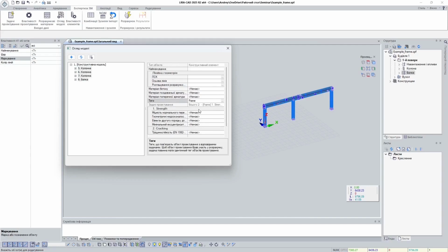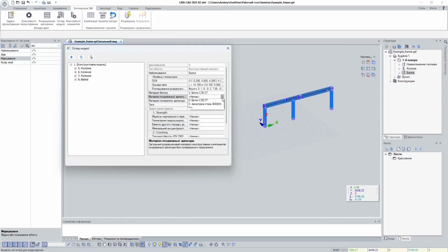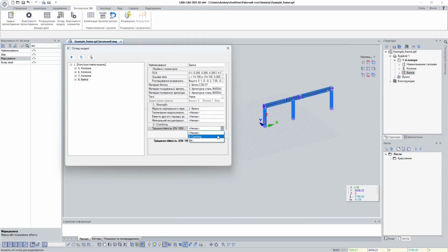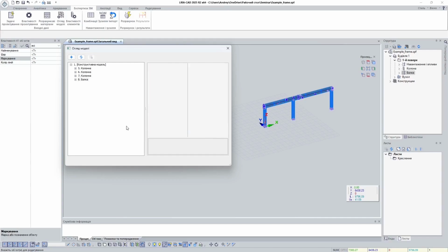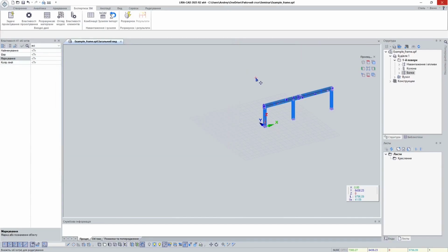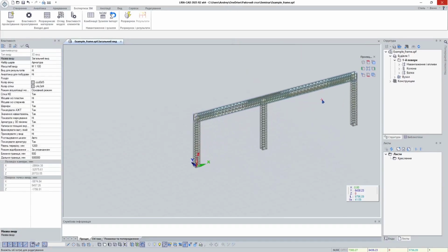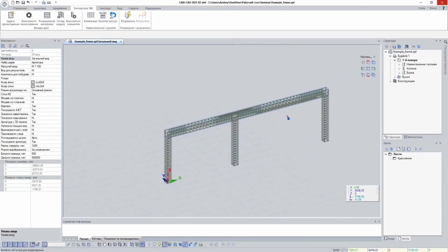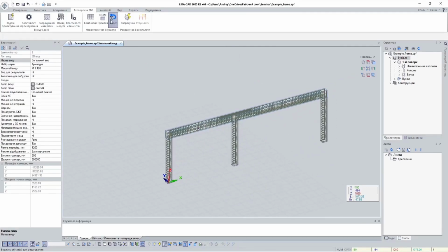The loads. Exactly. You need the loads and, crucially, the internal forces, the moments, shears, axial forces. Right. Where do they come from? You import them, typically from a LIF file. That's the LIRA-FEM file, the results file from the finite element analysis run in LIRA-CAD. Okay. When you import this, the system automatically creates calculation sections within the expertise of reinforced concrete structures environment for all your elements based on the FEM results. And the load combinations are set up based on the relevant standards, like RSN.